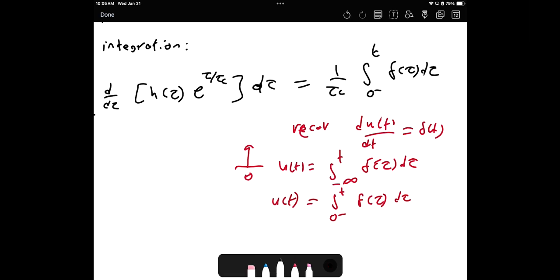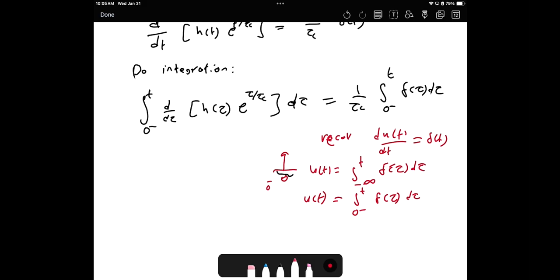Because our target is to include, when we do the integral, all of the area of the impulse. So when I make it 0 negative, I'm including all of the area. But if I made it 0 alone, it would be indefinite. If 0 positive, I will not include it. We call these limits in math 0 positive and 0 negative. So when I say at 0 itself, I'm not including the impulse if I make it from, for example, 0 positive. Therefore, it will be u of t.